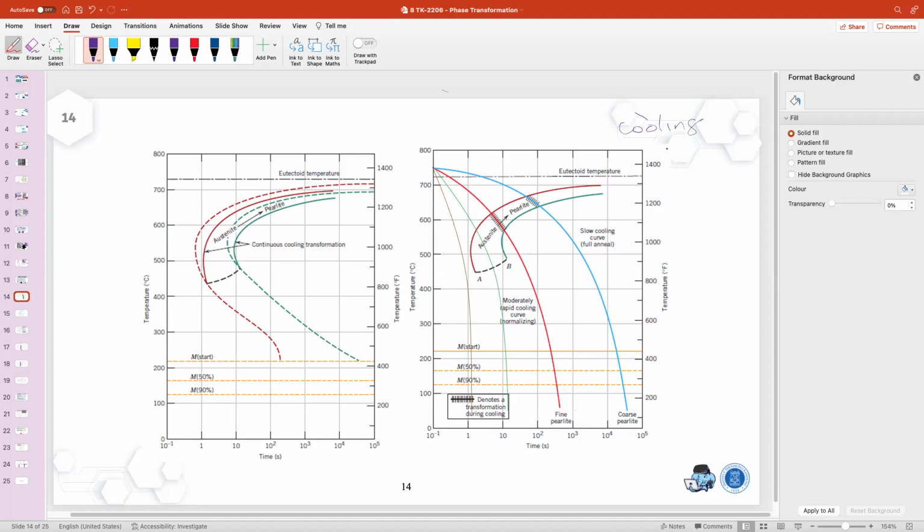To get the cooling rate is as simple as delta T divided by delta time. Okay, but however, the time is in logarithmic. So you have to be careful about that one. Be careful, the axis would be logarithmic. Okay, so that is the cooling rate.